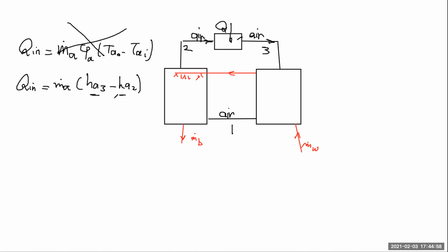So the enthalpy, why the enthalpy? Because the enthalpy is a function of temperature and omega, or phi, temperature and humidity. So you are considering the humid air condition here. The trick I would like to mention here: when you are talking about the energy balance and mass balance, there's no problem. They are basically the same. Here we should have some sort of m dot pure water as well. So the same conditions of air coming in with its enthalpy, water leaving with enthalpy, water is coming in and leaving as it has recovered some of the energy of the hot air.